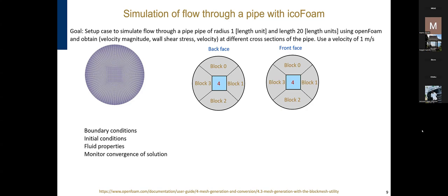So for the pressure, we can fix the outlet, for instance, to be equal to maybe atmospheric. And then we can back calculate from there throughout the whole region. So basically, we are saying to the solver that, hey, come up with a pressure that makes sure that mass is conserved, and then only the difference between the pressure at the exit and the pressure at the inlet should actually agree.